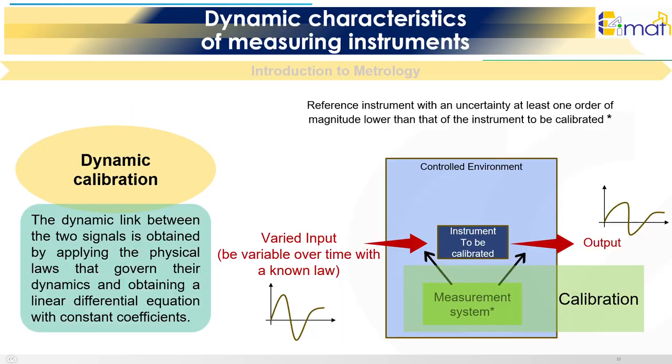Dynamic calibration is required when the input varies over time according to a known law. The dynamic behavior of the measurement system is modeled by a linear differential equation with constant coefficients. By solving this equation, we determine the operational transfer function, which describes how the system responds to time-varying inputs.